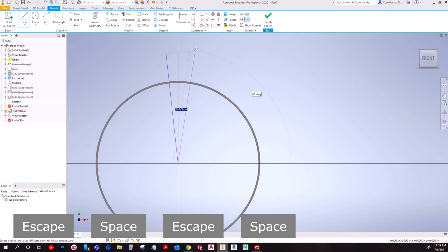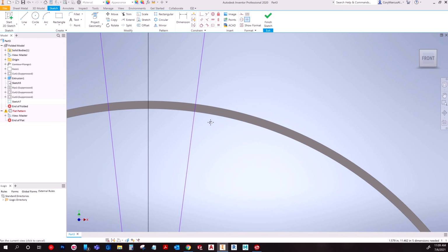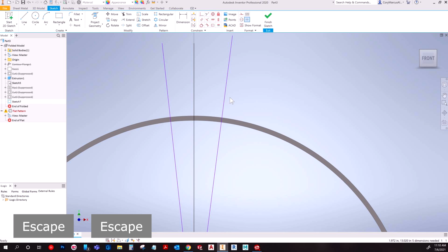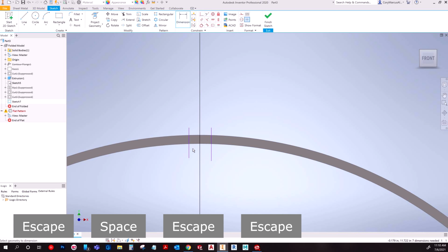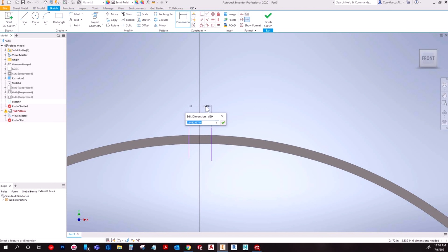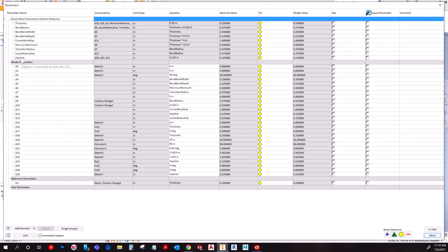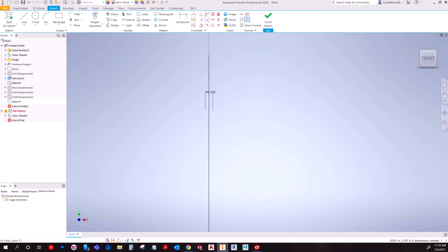The idea is that when you're looking at sheet metal, it's supposed to have a straight edge, always. So what you would do, I take that back actually. What you would do is draw two lines parallel to each other, and then you could manually go in and type in gap size, and that's Pascal case, just like when you're looking at the parameters for it. It's gap size. Now this is a lot more work, but for some reason some people do this, so I'm just pointing out that you could do it this way. I wouldn't exactly say do it this way.